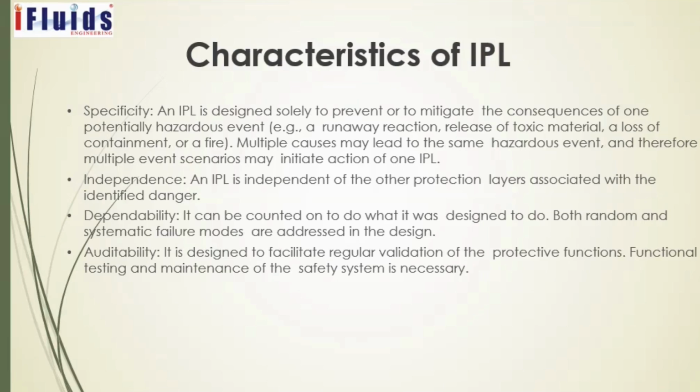Characteristics of IPL. Specificity. An IPL is designed solely to prevent or to mitigate the consequence of one potentially hazardous event: a runaway reaction, release of a toxic material, a loss of containment or a fire. Multiple causes may lead to the same hazardous event and therefore multiple event scenarios may initiate action of one IPL.